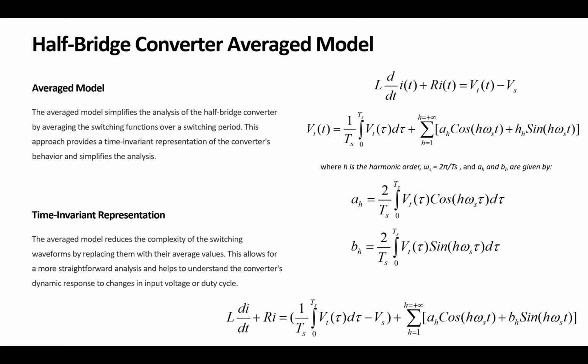Multi-level inverters, the advantage that they bring us is that they would give us less distortion at the output, so we have less harmonics at the output, and it would give us more capacity for delivering power to whatever application we have. Because of the less voltage stress that the switches have in a multi-level inverter, we could go up on voltage generally.